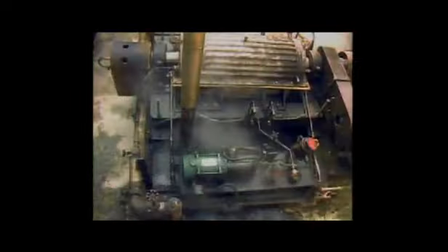Some pumps need a greater supply of lubricant to the bearings, so they use a forced feed system. For example, this system pumps oil through these lines to constantly supply oil to the bearings. The system also has devices that filter contaminants from the oil.